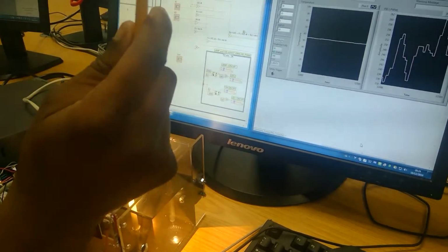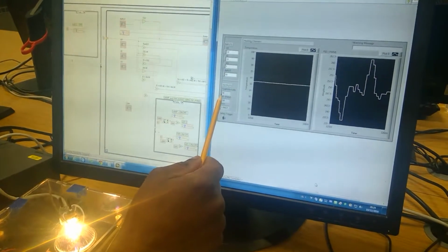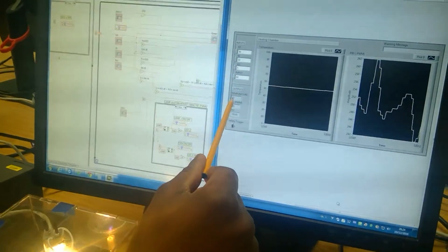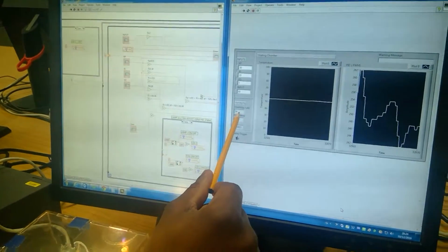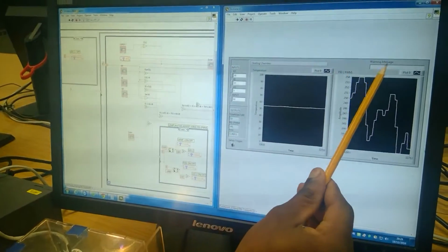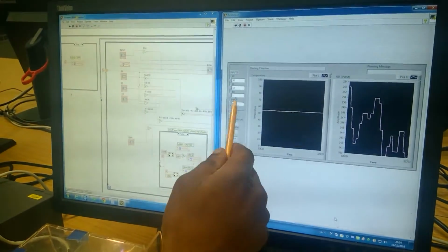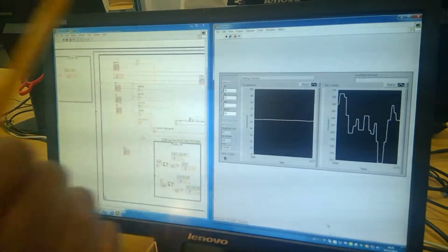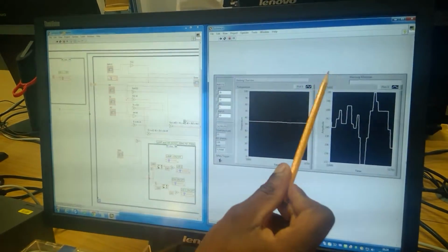So as you can see, just a few seconds to indicate that the temperature is above 55 degrees. Also, one thing you must notice is that because our temperature is rounded off, the error threshold is 55, so before the error message pops up, the temperature will have to be at a value of about 55.5. We'll see that very shortly.